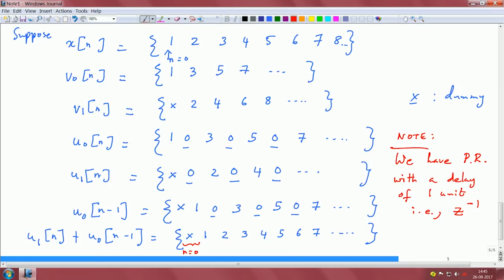Okay. So, now the real question is, this is a very simple 2 channel filter bank satisfying the perfect reconstruction property, and of course we have considered only delays as some of our filters, but in practice it may not be the case, because you may have to filter out certain components in the low pass, some other components in the high pass, and then come up with reconstruction filters. So, it is not very straightforward like the way we looked at the delay filter bank, because the filters can be quite sophisticated.